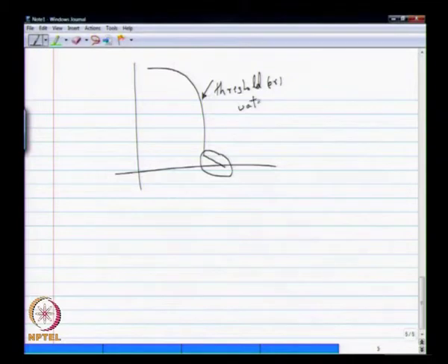and this is pretty much controlled by the random properties of the matrix. Minimum distance does not play a big role here. There are good reasons for that, people have analyzed it. Then you will keep on going down, and eventually the minimum distance will start to play a role. This is called the error floor region, and minimum distance plays a role here. So minimum distance is important for this.